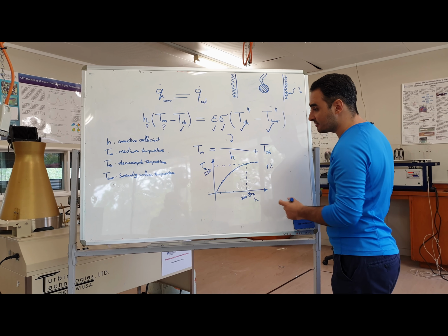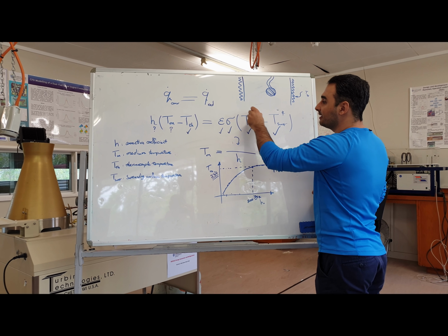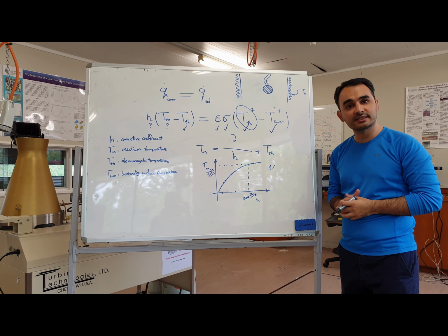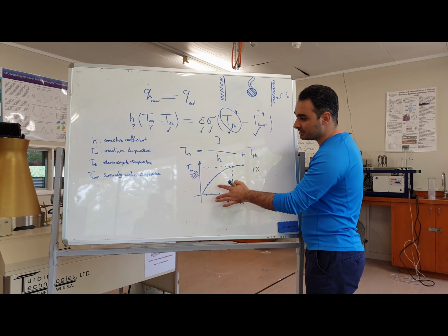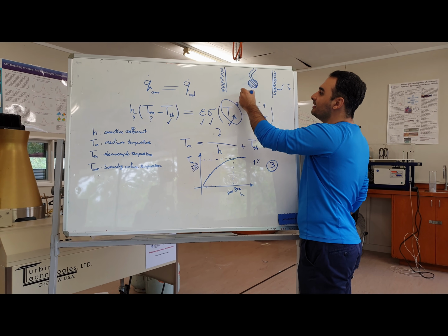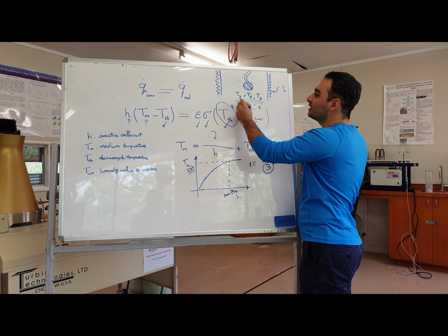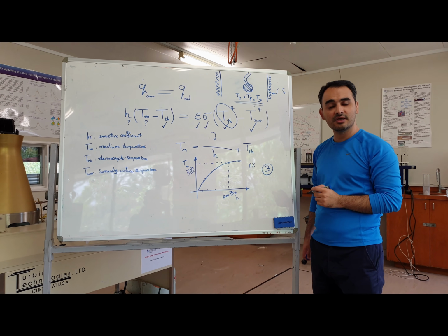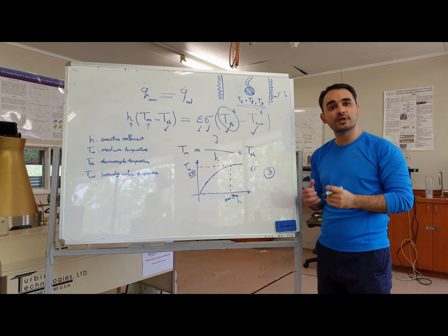You're going to record this value, and then compare this value with the Th from the thermocouples and discuss why they are different, and show me what is the effect of different thermocouples. And you need to repeat this for the 3 different thermocouples we have here. We have T7, T8 and T9, which shows we have 3 thermocouples inside, and you're supposed to do this process for those 3 thermocouples and compare those thermocouples and the results we are getting from them.